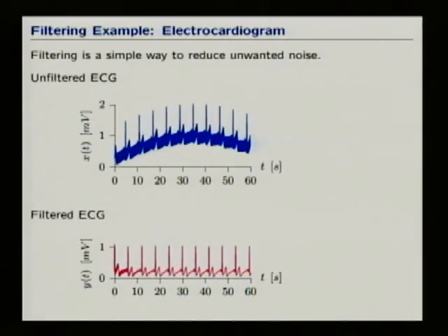no one in their right mind would generate an EKG machine that didn't do this, right? I mean, that's just built into the pre-amplifier that's attached to the electrodes. So the point is that filtering is a very important application of Fourier transforms. We can take an arbitrary signal and often get a lot of insight into what we would like to preserve and remove by thinking about the Fourier transform. Insights that you wouldn't get by looking at the time waveform.